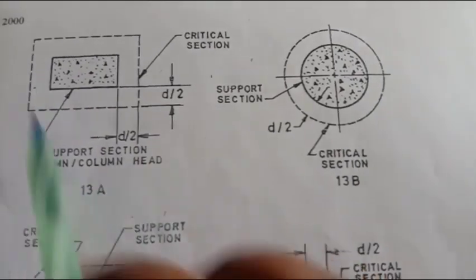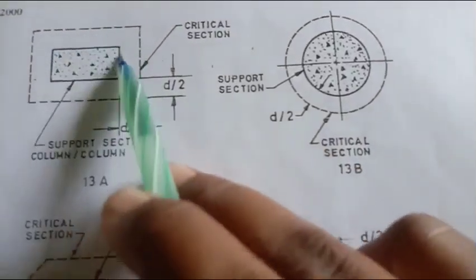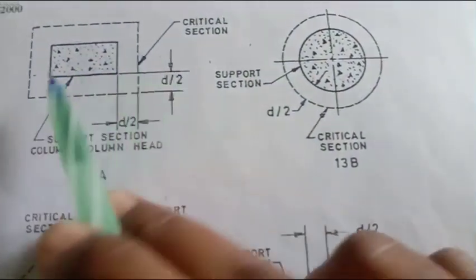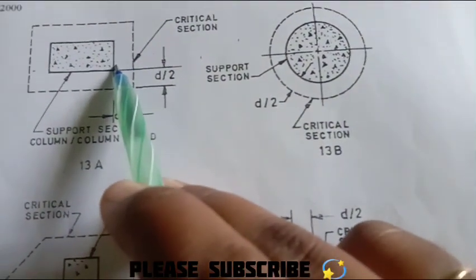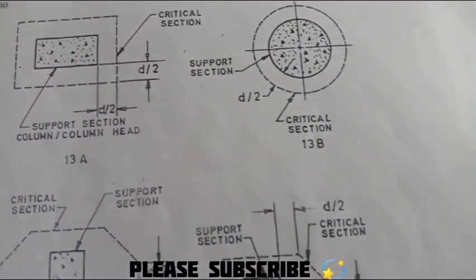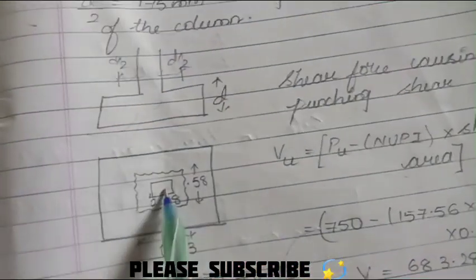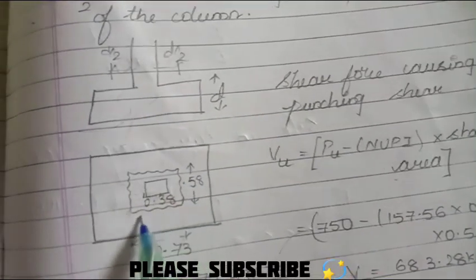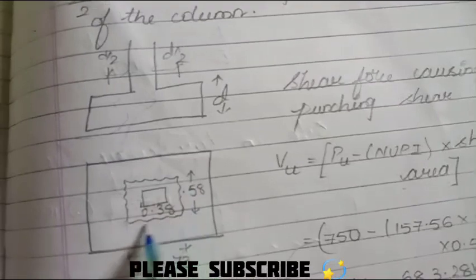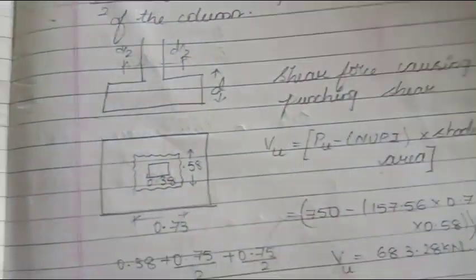For the support section, the column for the footing, the critical section is at a distance of d by 2 from the face of the column. Okay, distance d by 2 along the periphery, that is along all the sides, you will have to calculate the d by 2 value. See, this is the column. You just have to draw this. This is the plan, guys, and at a distance d by 2 you are specifying some section around the column. That is going to be the critical section.